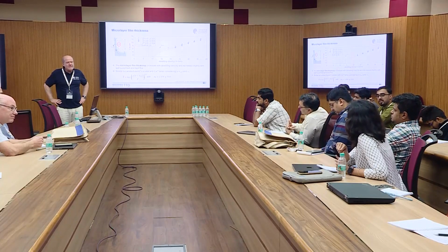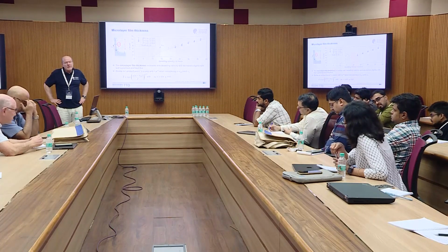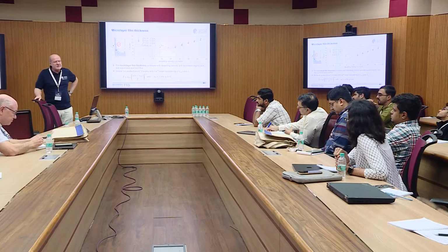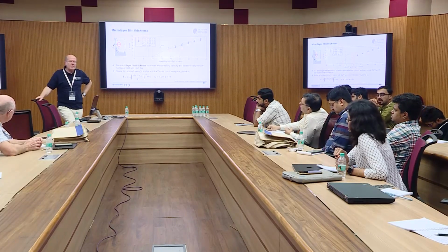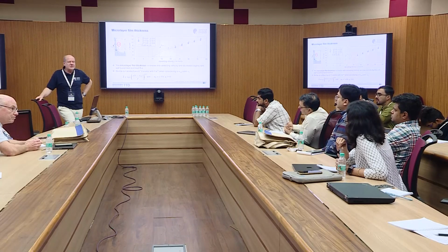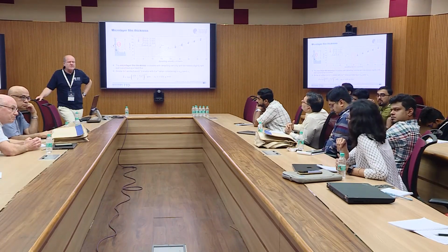Do you use the Schrage equation or something different? Yeah, we use the Schrage equation in our model. We have a sub-model for this contact line area, and then a CFD model for the larger area of the growing bubble. We call it the microregion model, with Schrage's equation and heat resistance at the interface. We combine it with OpenFOAM as a CFD tool.